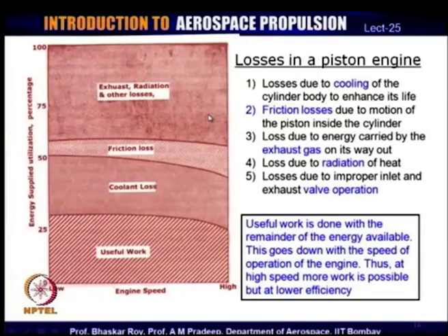Now, this is a penalty that you have to pay in an aircraft engine, because you do want a high amount of work supply, and as a result you have to be content with the fact that you may have to be working at a slightly lower efficiency, because the friction losses and other losses are somewhat on the higher side at high speed operation.